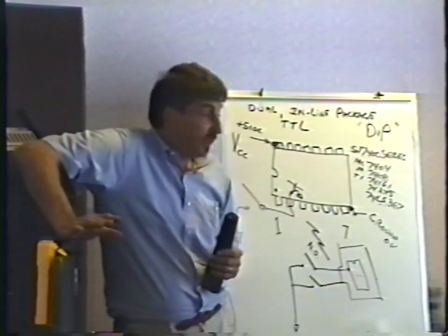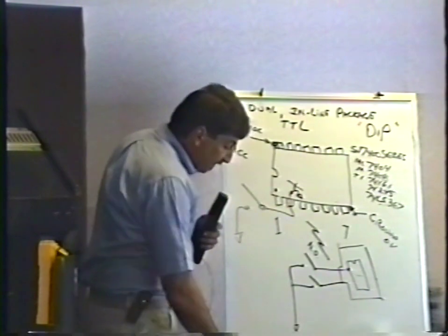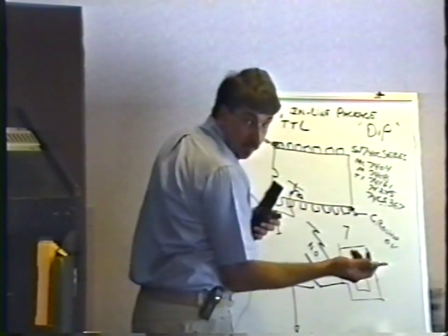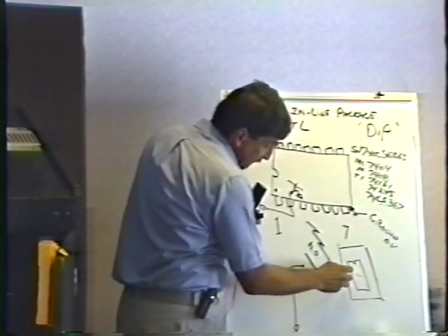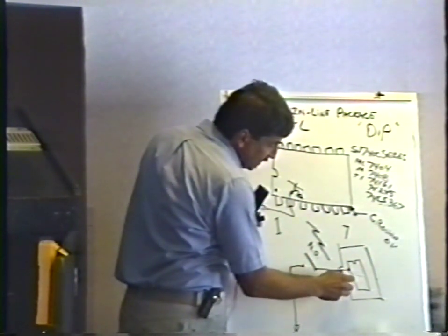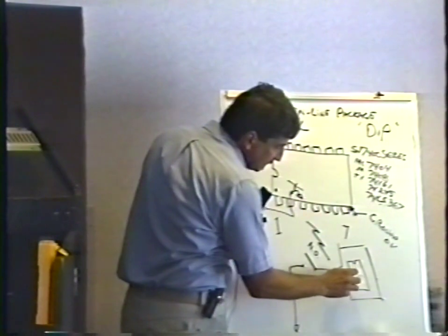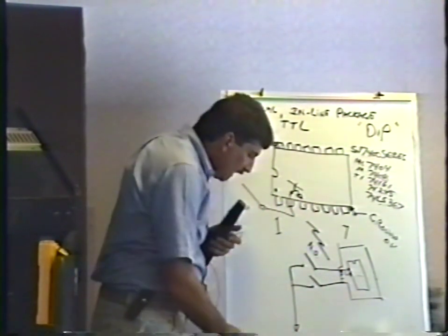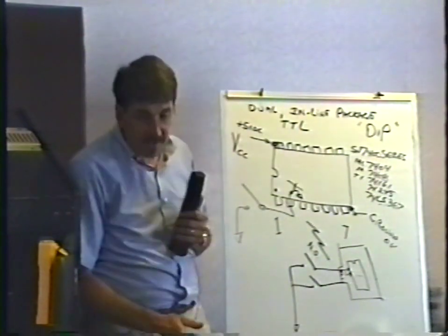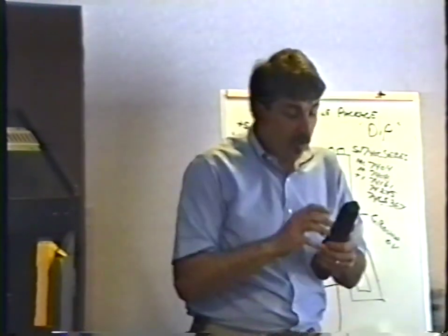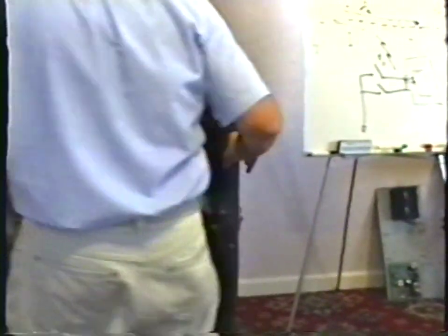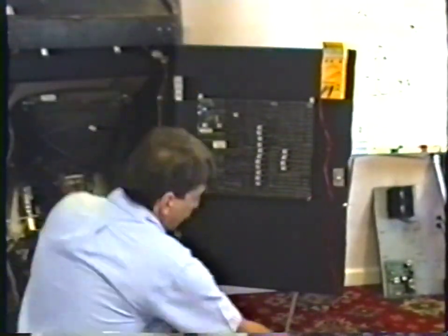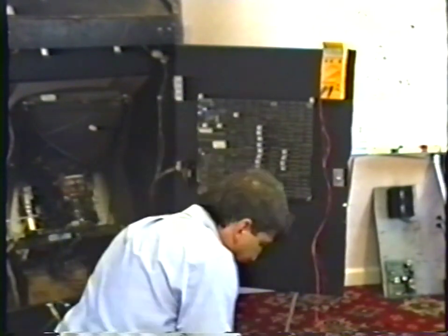Well, this is an unbelievably neat trick, and you can find the pin, by the way, if you don't have the schematic, which you probably don't, simply by following the trace back from the edge of the board, follow it back, and go right to the pin of the IC. Regardless of that, in fact, you can check them really fast. You don't even have to be very careful about it, since the power is off now. There's no power on right now at all. You don't even have to have the game hooked up.